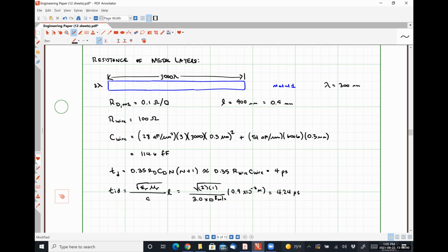How can I put this? For an N-well type resistor and all that kind of stuff, everything we built was so much longer than the intrinsic delay time that it really didn't seem to matter. Here, it's going to start to matter a lot. We're going to see that we are limited by the speed at which our medium can transmit signals.